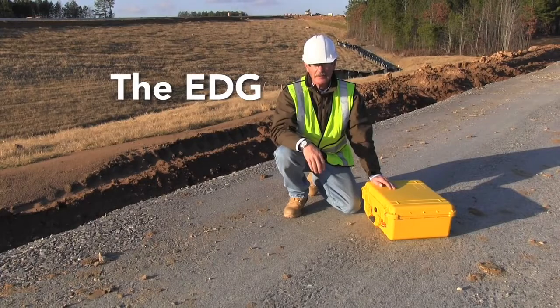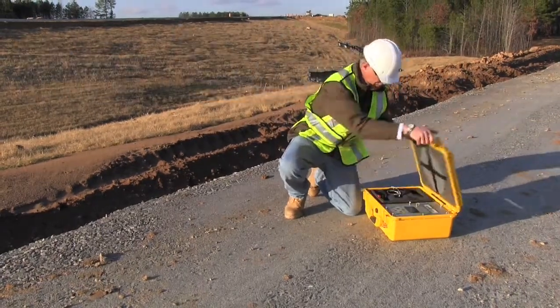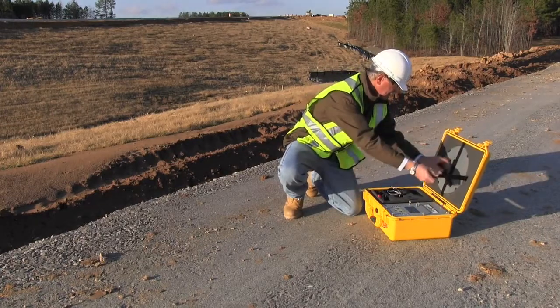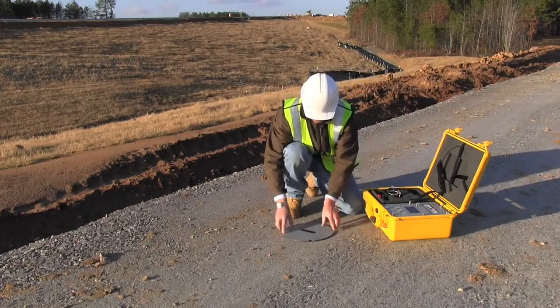With the EDG, a technician can perform a test quickly and accurately to get immediate values of density and moisture. Compaction values can also be generated if Proctor test data has been entered into the gauge.